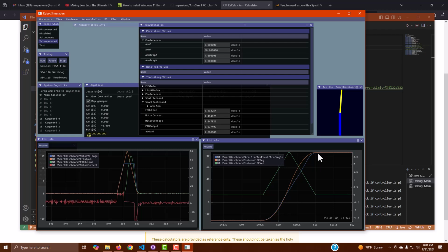The PID assures that we catch back up. But you see how much work the PID had to do here, because the feed forward isn't capable. We can't drive this thing up to 17 volts. It won't work. So the feed forward becomes inaccurate, and we see a sort of a deviation like this. So we can't just set this anywhere we want. It has to be a feasible value. You can certainly set it at less than the max. If 1.95 is max and you want 1, that's fine, but you can't make it 2.8. So that's what happens if your velocity is infeasible.